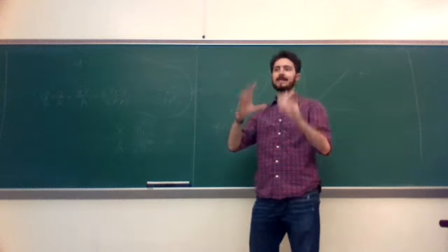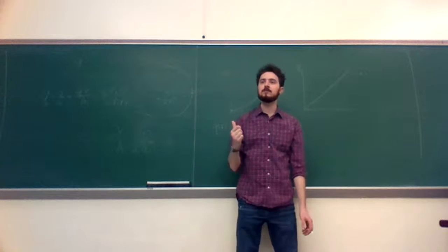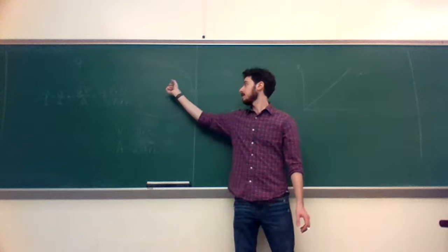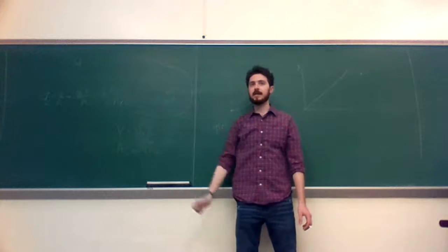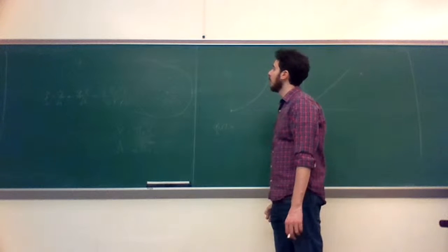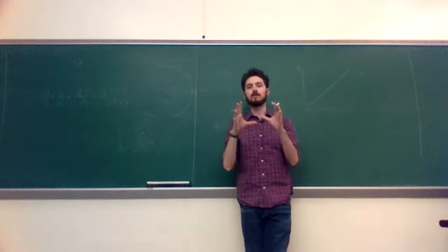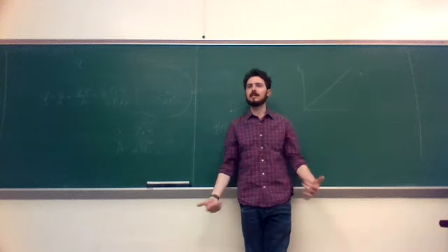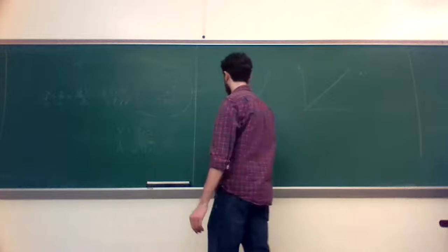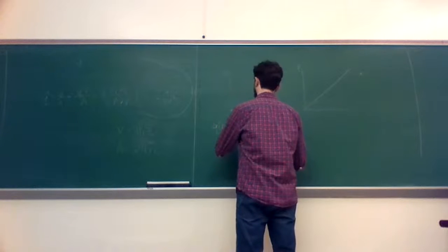Or you could say in the control volume bounded by that control surface, because there's no extra heat coming in, right? So there's no original heat flux or heat rate. So basically, in this steady state condition, if you've got heat passing through a control surface, it has to be generated within that volume. That is just kind of an application of first law that should be hopefully somewhat intuitive. So Q at r is exactly equal to Q dot,